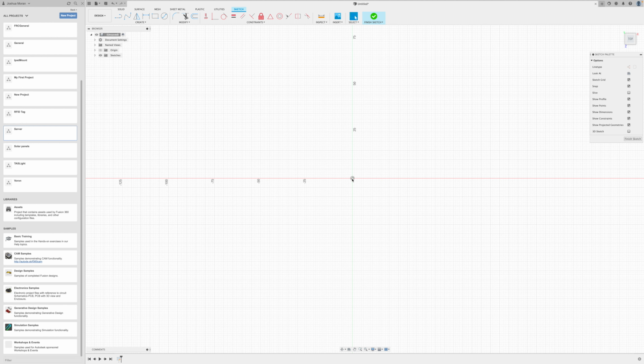Now what we can do, we can take our mouse, go up to the corner that says Create. So along here we have all the tools we can use in Sketches. You can click on these little drop down menus and they give you a lot more. Might look pretty confusing and scary, but you'll get to know it soon. So we need to go Create, Rectangle, Center Rectangle.